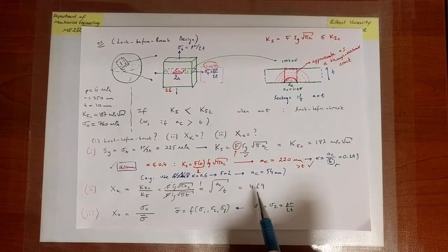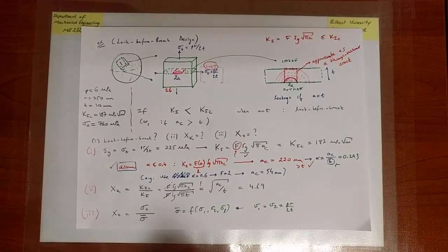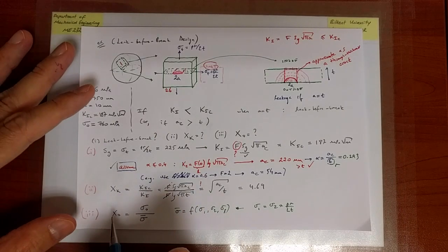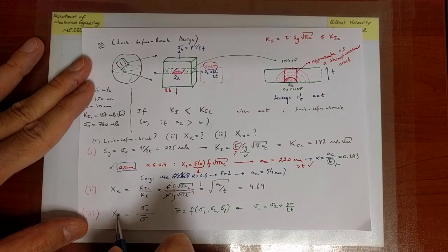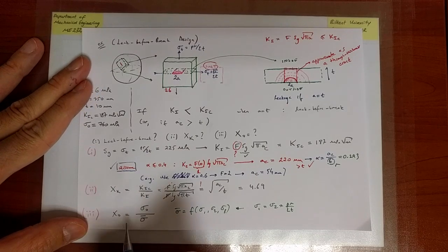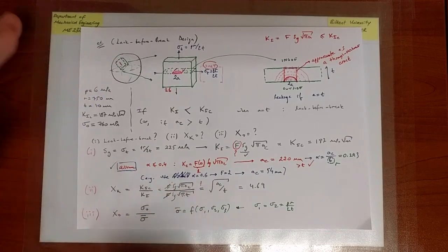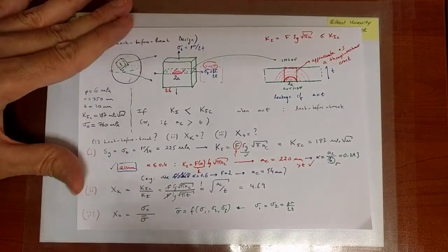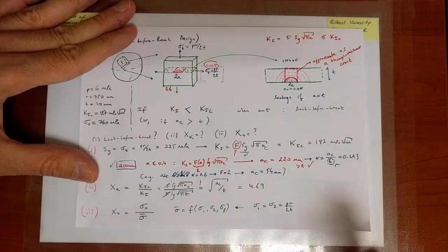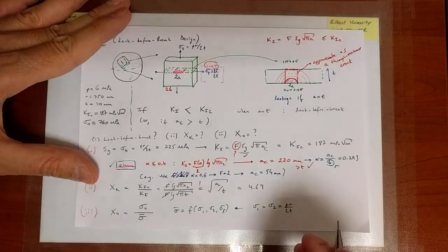Let's get back to what I was saying. I may not want yielding to occur either, so I'd like to check my safety factor against yield as well. The way we do that is we calculate the safety factor on yield as the yield strength divided by the equivalent normal stress. So remember, the criterion that we use to check for failure, either for brittle or ductile